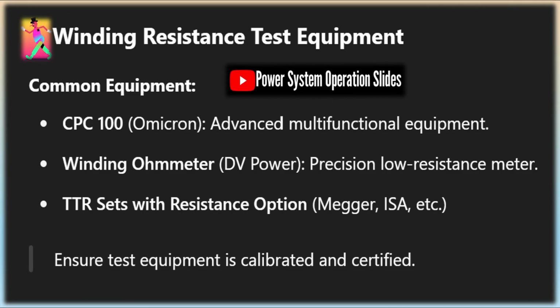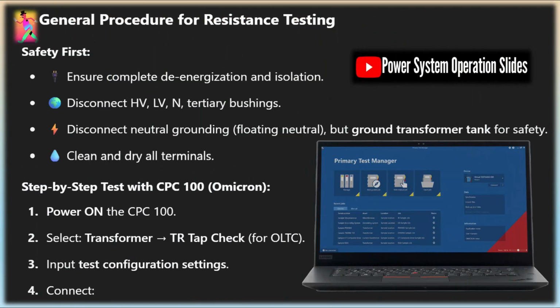Perform demagnetization before disconnecting leads. Importance of demagnetization: why is it necessary? DC current aligns magnetic domains in the core, causing saturation. On re-energization, residual flux causes high inrush current. Inrush can be up to 20 times rated current, stressing protection relays and windings.